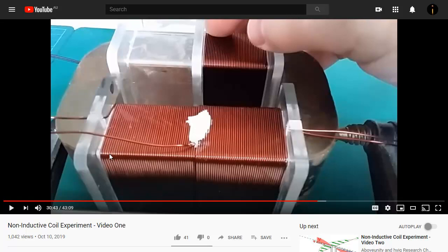So one coil underneath, full length, top coil here, only half the length. We had ends tied up here. So the current going up that way was the same as the current coming back down this way. And we had a lot of trouble trying to get any voltage on the end. And this is a problem because the coils are bucking.